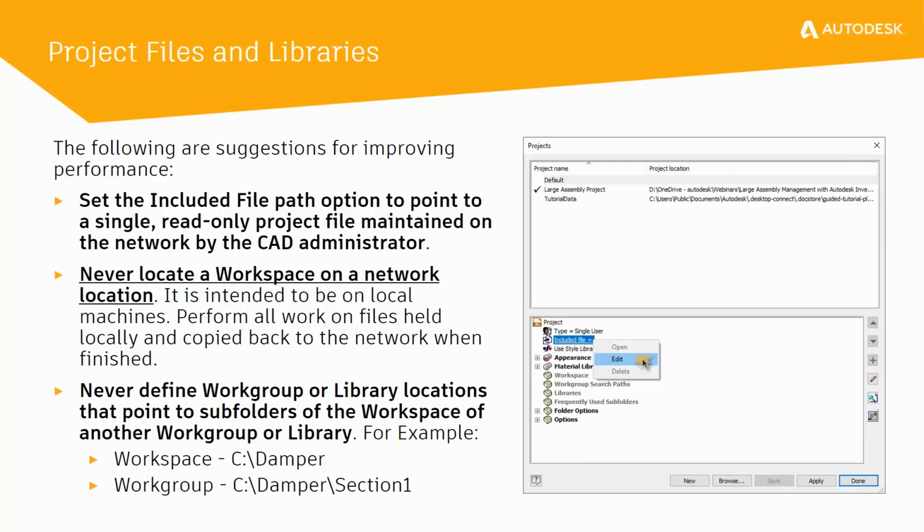The other thing you can do is to try to never define workgroup or library locations that point to subfolders of the workspace of another workgroup or library. So what we're trying to do is avoid intermingling workgroups and libraries across various other workgroups and libraries.